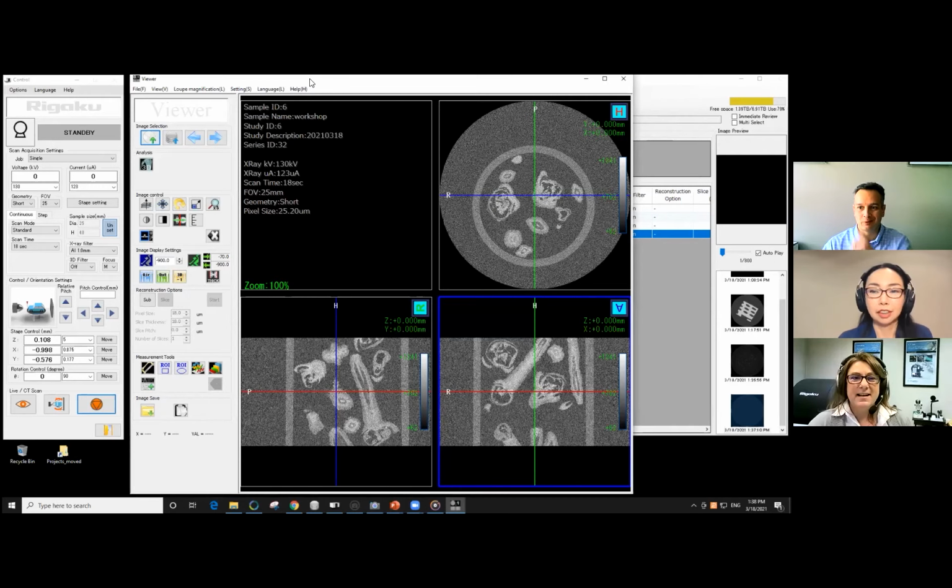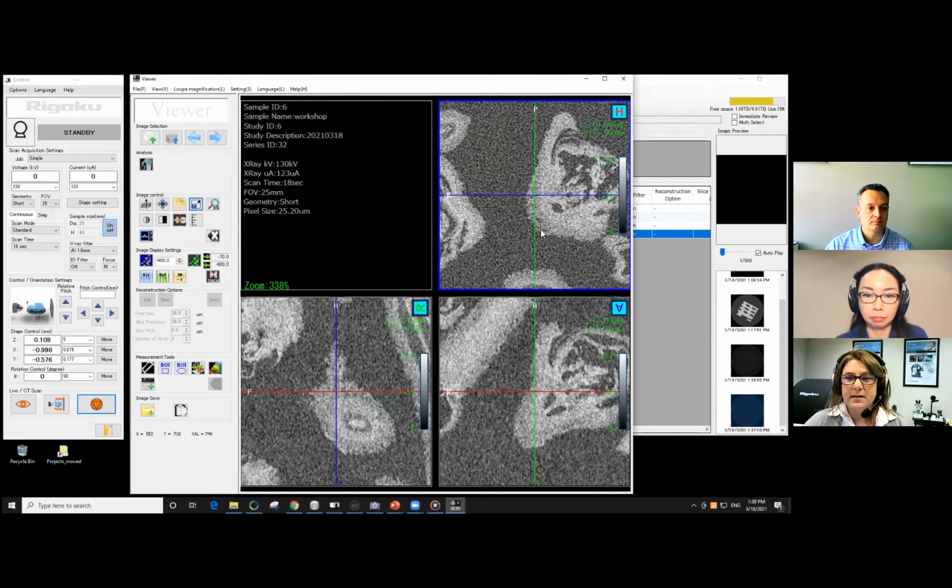Yes, there is. That's a good question. Basically, you need at least 2 voxels to see a feature. A feature could be an edge, or it could be something like these small voids in here. If that void is 5 microns, then you need at least 2 voxels of 2.5 microns to even see it. But ideally, it should be much smaller, say 1/4 to 1/5 for the voxel size.